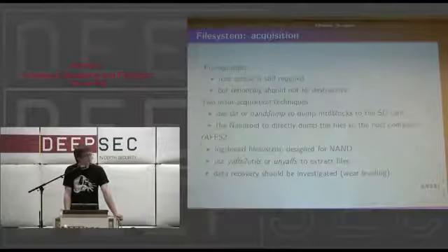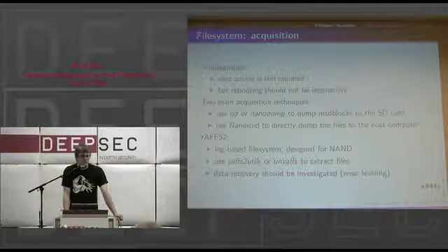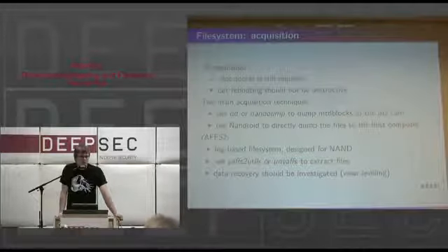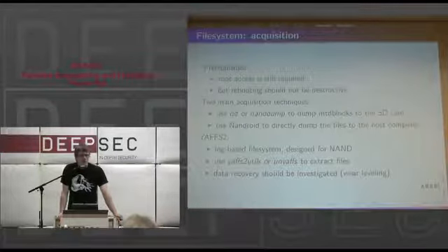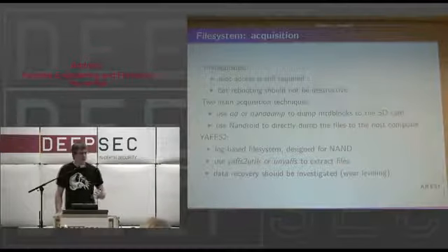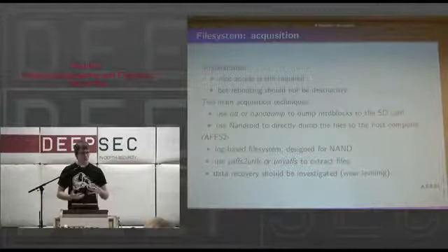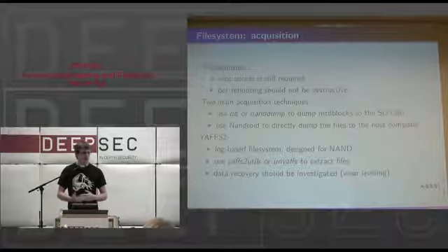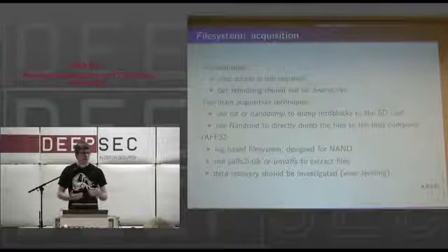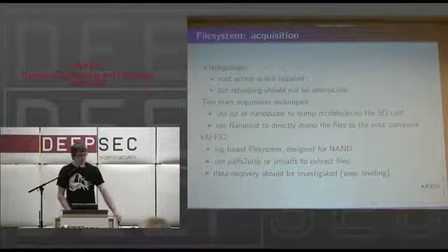I don't think so. I think these flash file systems, because erasing a block takes that long, they are using a background job usually to erase blocks, so it might not get much. Well, I've read the specification of the file system, and it could work. It depends really on the implementation, because unless you have the garbage collector running, the blocks shouldn't be erased. So I think it depends on how the file system is tuned. When does it trigger an erase because it's time consuming, and when does it stay as it is?